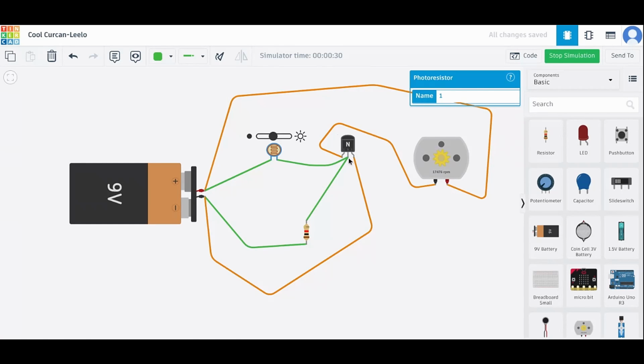The order of voltage that we are expecting here and the current that we are expecting there, based on that, we can quickly make a call on how to choose these two resistors. Okay. So the green loop is just a voltage divider, a controllable voltage divider. In fact, this is indeed a potentiometer, right? You have control over where you take the voltage, measure the voltage, right? So the green loop is just, let's say, a potentiometer.